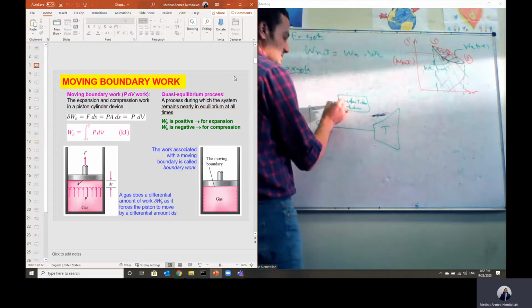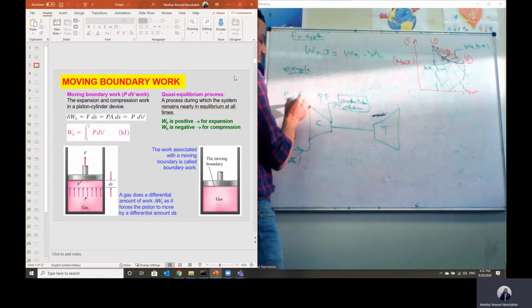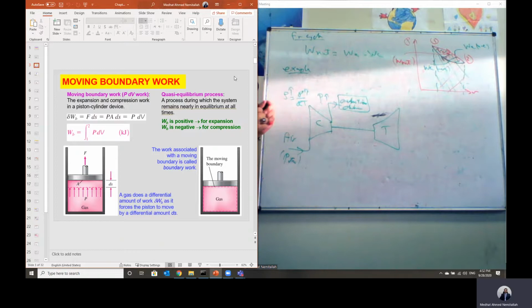So its pressure is raised here inside the compressor, and actually this is high pressure. So the density in this case will equal pressure divided by RT. Pressure is high, that means we have high density of the flow, which means we have a higher mass flow rate. Mass flow rate is density times area times velocity. High density means we have a higher flow rate.